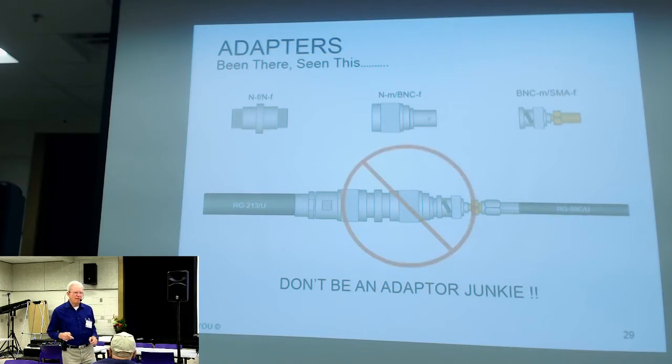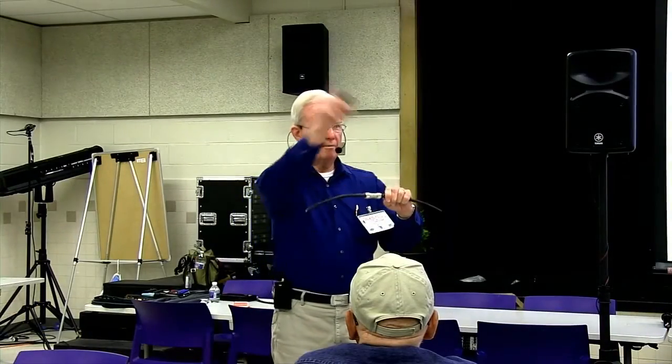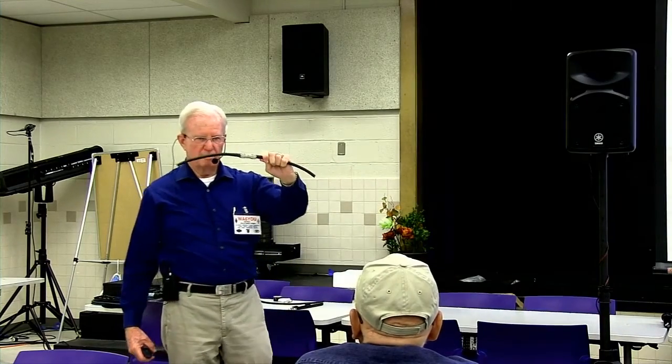Well, that's another fallacy. You actually have to put it on a TDR, a time domain reflectometer. I've seen everything from 6, 7 dB, but the 3 dB rule, no, it's not really. That's a fallacy. But just don't stack them. Now, what you can do, though, Mike, is keep it in the family. Type N, Type N, Type N, that's okay. It doesn't even see it. It's when you start mixing families.